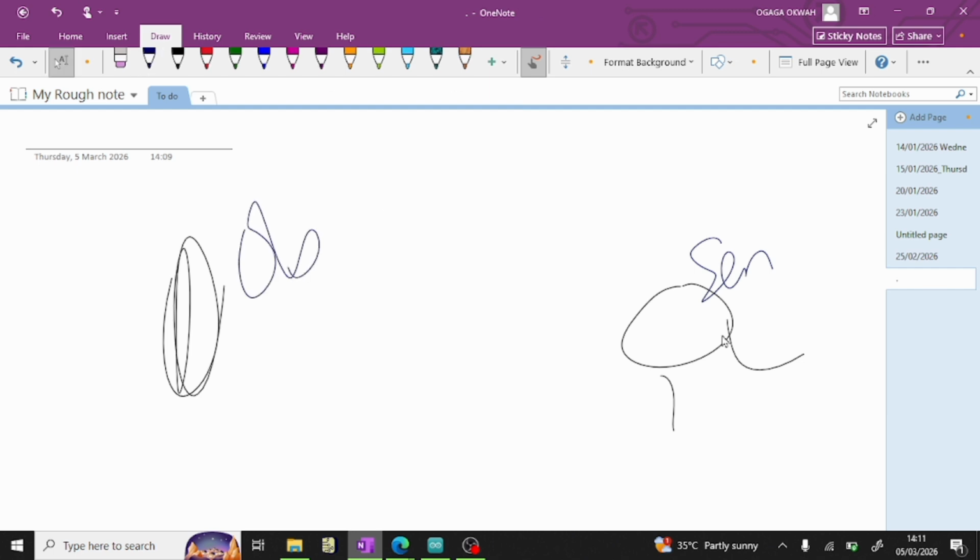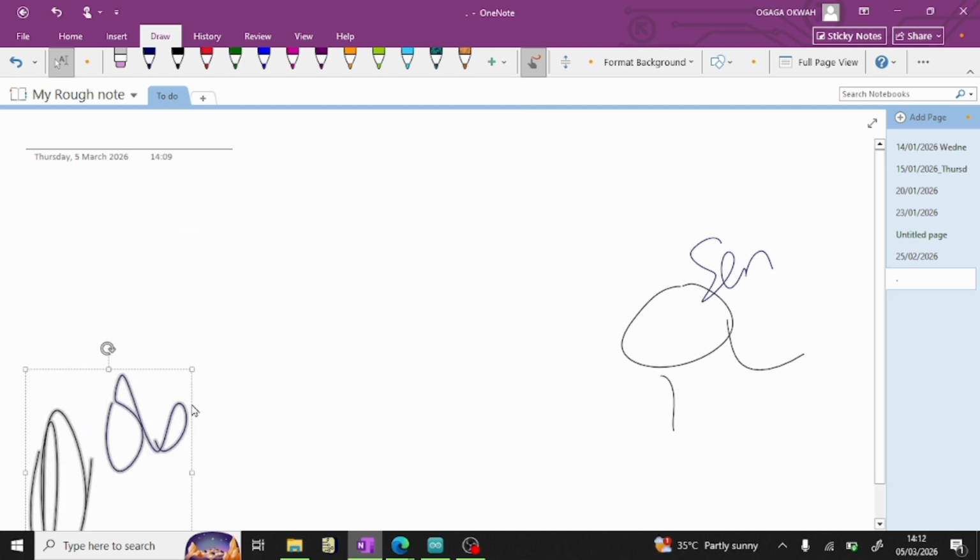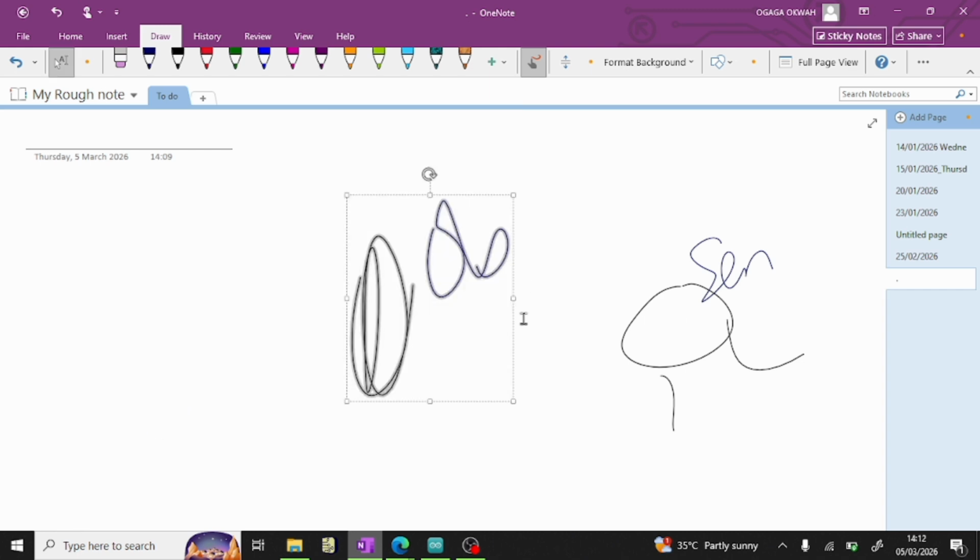Now, if this object is not here, of course, no alarm. But when the object gets in front of the sensor, how long does it take for the sensor to detect this? Once the object comes within the range where it can be detected, how long does it take for the sensor to detect it? That is the inhibit time.